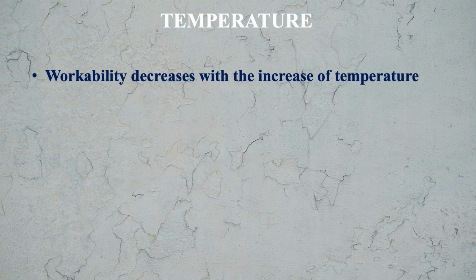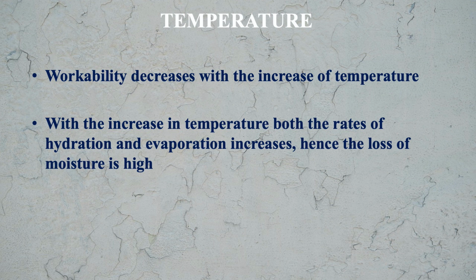Now let us see the effect of temperature. Workability decreases with increase in temperature. Means workability will go down as the temperature increases. With the increase in temperature, what happens? Both the rate of hydration and the evaporation of water increase. Hence, the loss of moisture is high.